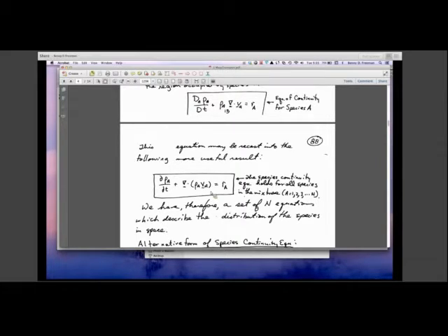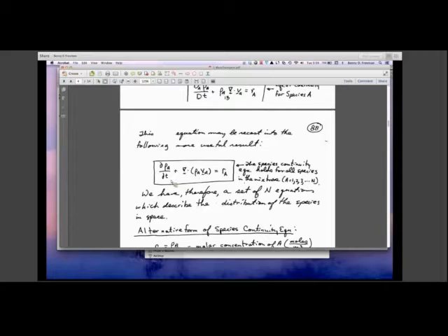That is what we wrote down without explanation at the beginning of our discussion of chapter 18 as the mass balance in any system which is at steady state and doesn't undergo chemical reaction, if it's a one-dimensional transport problem, right? Look at this. If it's at steady state, what is the value of this term? If there's no chemical reaction, what is the value of this term? 0. And then you're left with the divergence of the flux is equal to 0 in the absence of chemical reaction. And then if it's in one dimension, the divergence of the flux is d flux d z, whatever the dimension is. So this is exactly what we have been using previously.